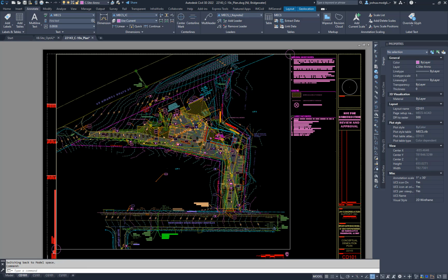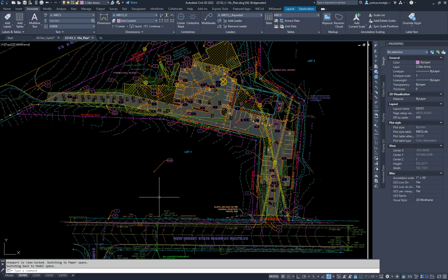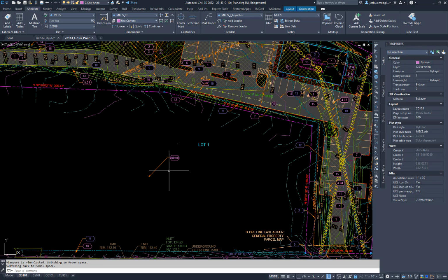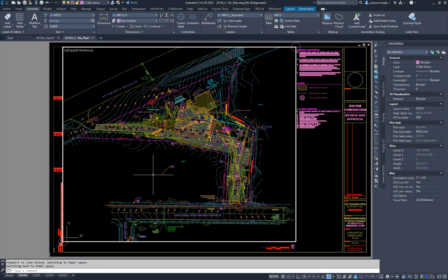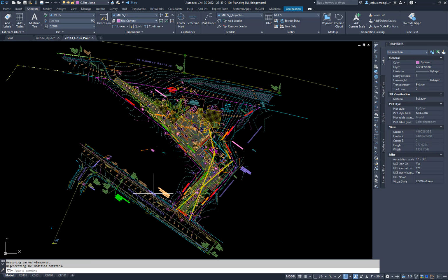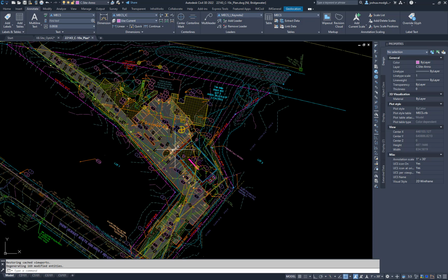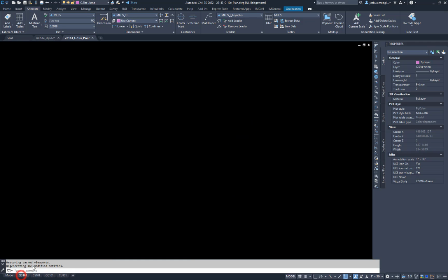It's more in this direction, but because I set the UCS for this view, I'm able to use these tools and have the landings and everything line up nicely. So I like doing that, and it's another reason why I like working through my viewport for annotating and the like. Now that you know your twist, you could come back to model space, but again, I'm not going to be working in model space. This is just too busy for my normal working.